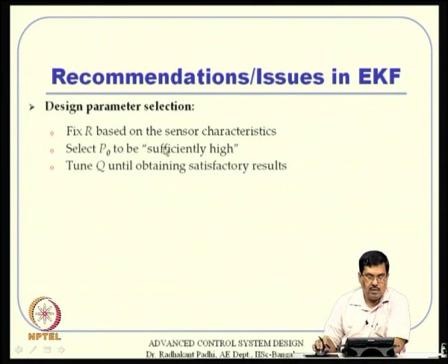A lot of times you will see in the literature these recommendations pop up. Remember the tuning sense: what you really need is an initial condition guess for the state vector, and other than that we need values for these matrices P naught, Q and R.